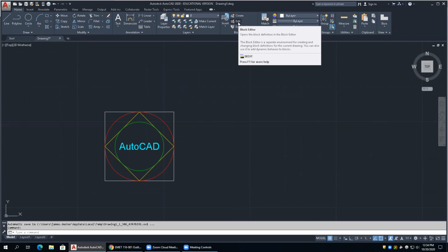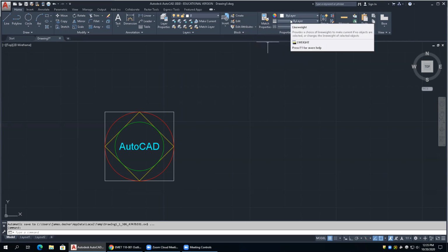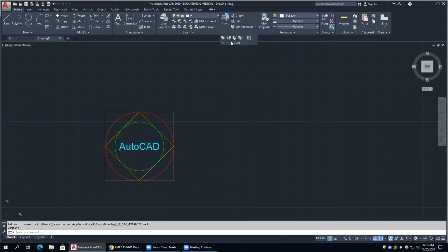You can add parameters called distance and angle and alignments and all that good stuff. Okay. So then the other commands that you see there, these are attribute commands. So there's your attribute command, and then this is how you create attributes. So most of these commands right down here deal with attributes, so we're not going to be dealing with those. So interestingly, the one I talked about called the W block command initially, that's not on there, and that's a really important command. So we'll take a look at it.